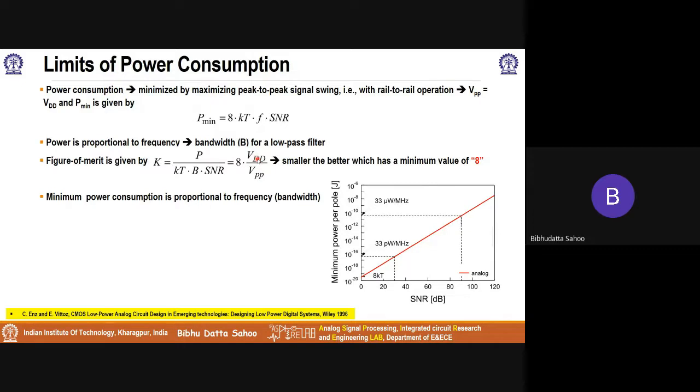But at the end of this course, I will show a circuit which can actually extend the VPP all the way to VDD. That is a digital technique for realizing something. Although the VPP still cannot approach VDD, because it is a digital circuit, it can swing all the way from VDD to ground. But I would not say that the output signal swing is VPP equal to VDD.